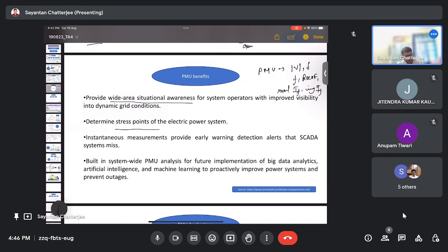These can be reconstructed to the current magnitude and phase angle. The main necessity of using the real and imaginary parts is for real-time analysis like state estimation, which is a real-time monitoring aspect. In WLS, the weighted least squares estimation technique, we need to invert the Jacobian.